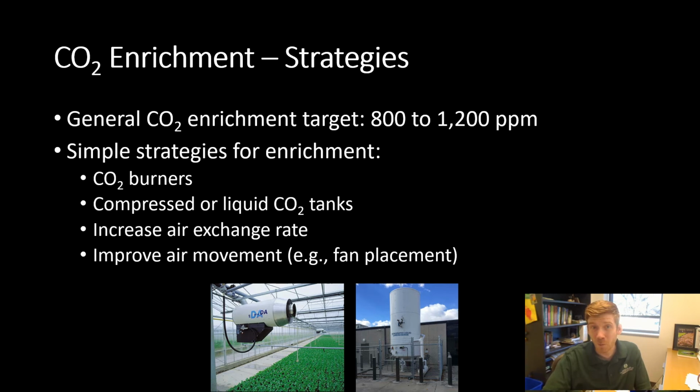However, you must be aware of how this will impact your environment, especially in terms of heating during the winter months. Lastly, improving air movement through proper placement and sizing of fans can be another excellent way to ensure that CO2 concentrations are replenished within these dense crop canopies.